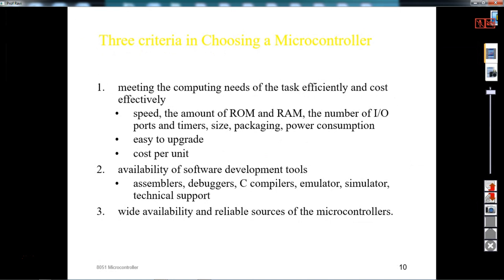And when you are trying to write programs, like we said, on-chip ROM is available. ROM means ROM or EEPROM. When you are trying to dump the program which you have written on your computer, you should have the software development tools, like Keil, an assembler, which converts your assembly language or C language program into low level, and that low level program has to be dumped onto your ROM.